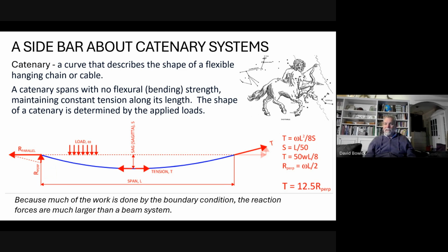Like, start watching for catenary systems and think about that. I mean, L over 50 for lots of them is overly conservative, but if you think 10 times, whatever load is applied normal to the surface, the in-plane load is 10 times that force. Okay,